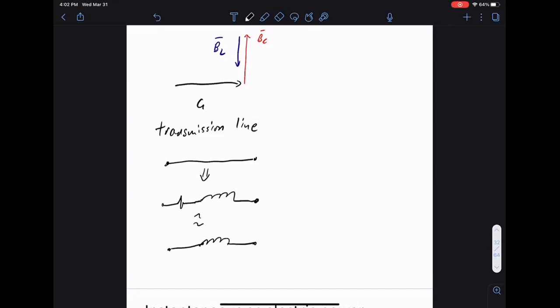So from, let's say, the substation to your home, basically it looks like an inductor. The line to your home. So this is the load. This is your home. Okay. So often we don't want very large inductive lines. The line being very inductive can lead to some issues operationally. So often what you see close to your home is that you install a capacitor to cancel this out. Install it close to your home.